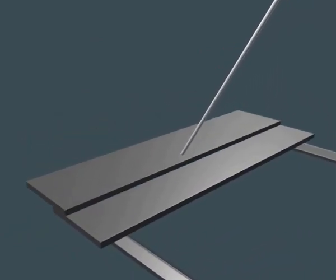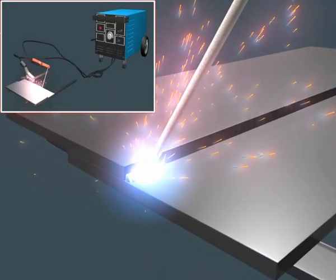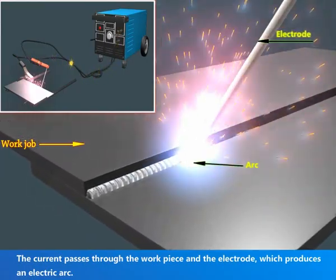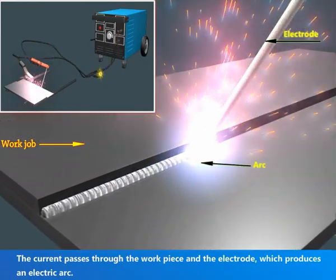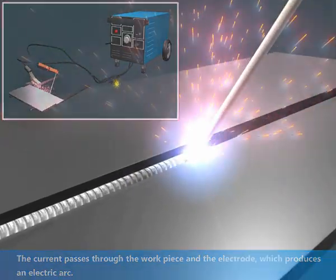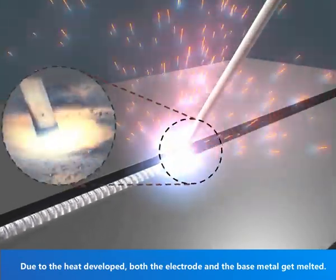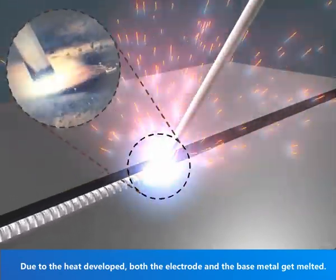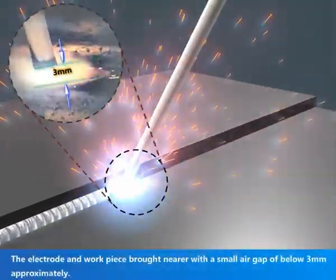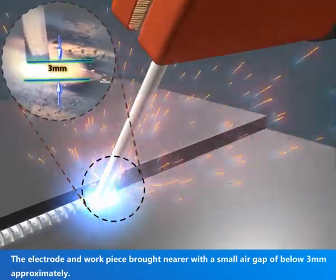In arc welding process, an arc is produced between electrode and workpiece. The current passes through the workpiece and the electrode, which produces an electric arc. Due to the heat developed, both the electrode and the base metal get melted. The electrode and workpiece are brought nearer with a small air gap of below 3 mm approximately.